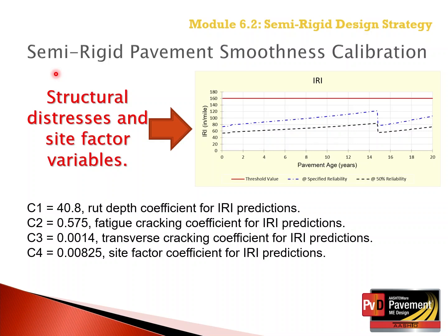And again, just a reminder: the values for the calibration coefficients for smoothness, reflection cracking, and the other distresses of semi-rigid pavements may vary between different publications of the MEPDG Manual of Practice, depending on the results of the more recent global calibrations.